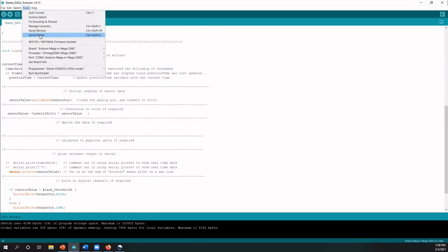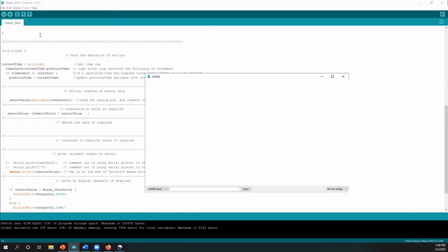So I'm going to go to Serial Plotter, and I'm just moving my hand up and down over the Arduino, over the distance sensor. And you can see this trace is going up and down between about 0 volts and about 5 volts. So it's using the full range. I'm going from maybe about 10 centimeters to 30 centimeters. That's about 4 inches to, I don't know, metric is difficult. But kind of a typical range of motion, about an arm length at most.